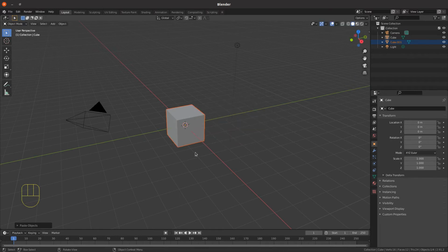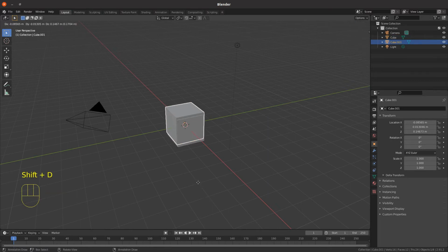I'm going to escape and delete that with Control Z, so we're back to just the original cube in the outliner, because Blender offers a more efficient function, which is to duplicate the cube, and that's using the shortcut Shift D, because that places it already in the move command as soon as you've duplicated it, so you're not stuck with the object sitting exactly over the original one you're copying.